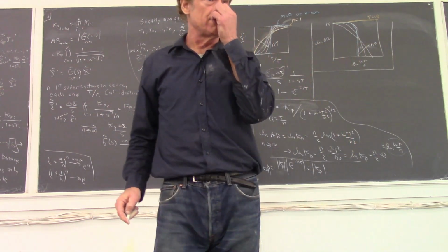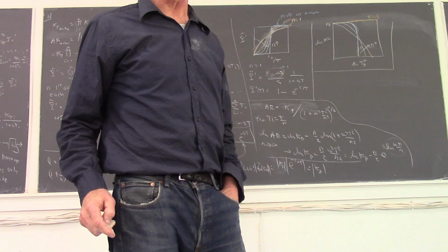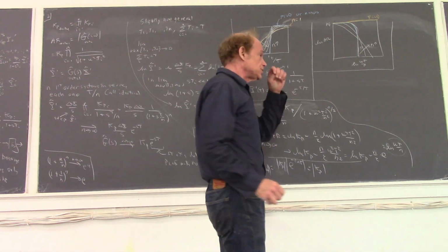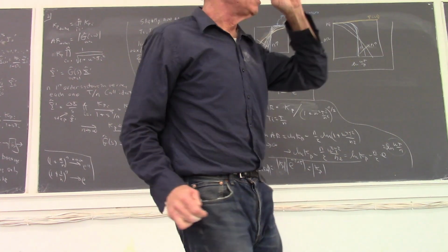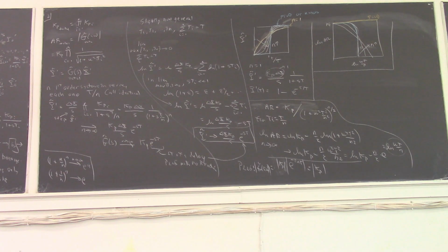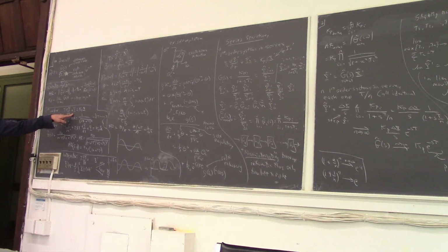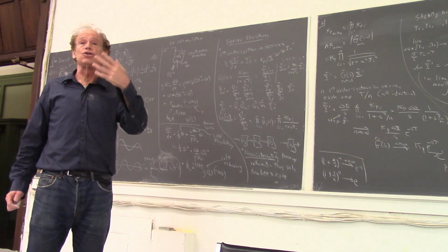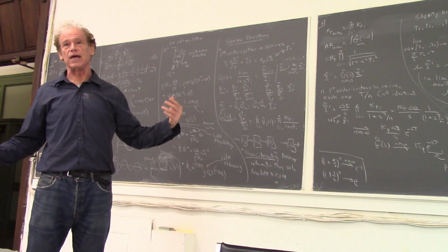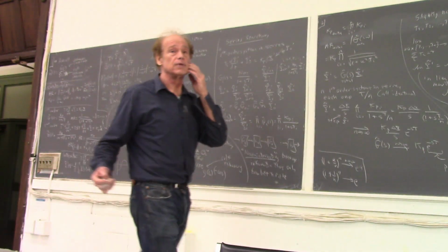Questions? Was this for a first order reaction? This is a first order system. So it's either no reaction or a first order reaction, or a linearized version of a higher order reaction. Because, again, we assume that the first order system looks like this. So this particular term, this y, comes from the outflow and from a first order reaction. And that's why I got the t where I got the t. First order or an effective or linearized first order reaction. Once I have something that's nonlinear, then it's nonlinear, so I can't use the same machinery unless I linearize. Other questions?